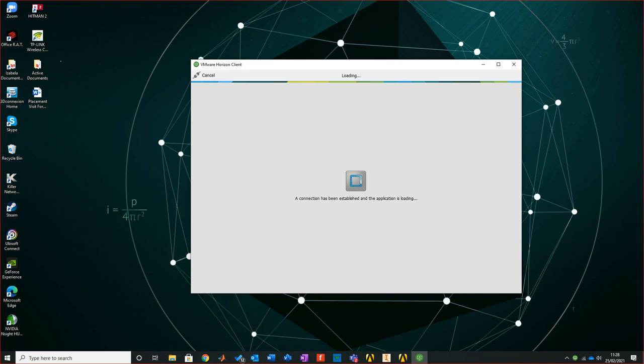If you're operating in millimeters, everything must be held in millimeters. You can't go, right, that's 10 millimeters and then that's, I don't know, 500 centimeters, or that's 1 meter, because it'll presume that they're all the same value, or the same unit, sorry. You do need to keep that in mind, because this stuff doesn't care about what you're trying to do. It just cares about producing a result.